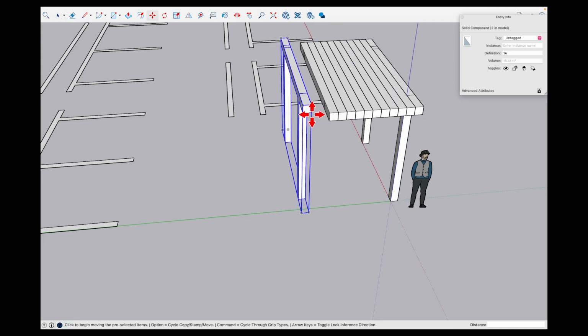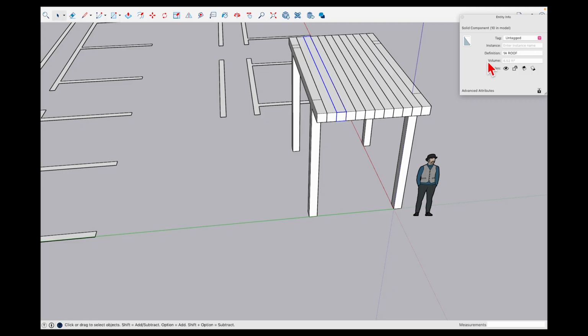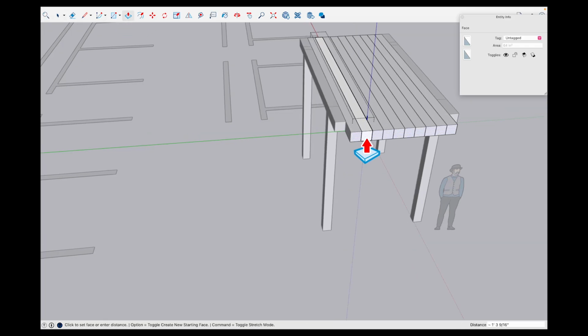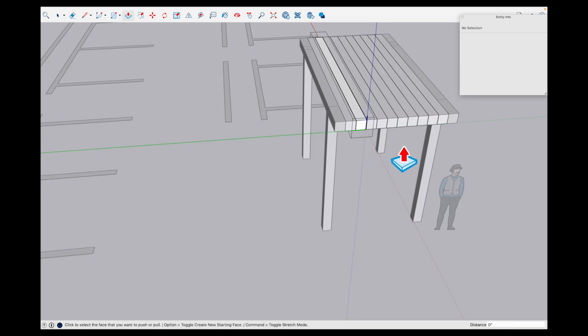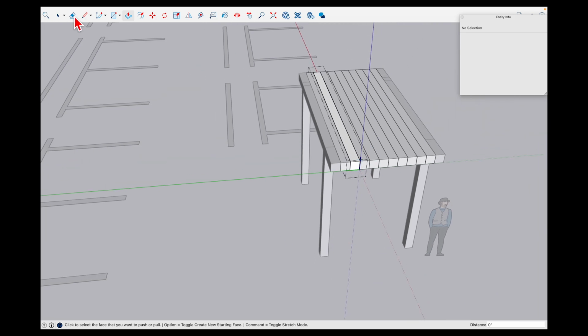So just a few things I want to touch on to really educate you on SketchUp is that the main point of this program is to model things three-dimensionally quickly. Speed is the biggest thing here in SketchUp. And if you click here, you'll notice that this is called a component. And please don't do this, but this is what a component does. If I were to double click into that component and start editing, let's say push-pull, it edits everything that's a component within that same family. Okay, so anything that's the same as this little beam here, this little roof condition, it will be changed with it. Okay, so that's why we have components. It keeps consistency throughout. All right.